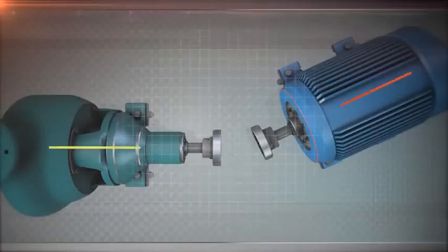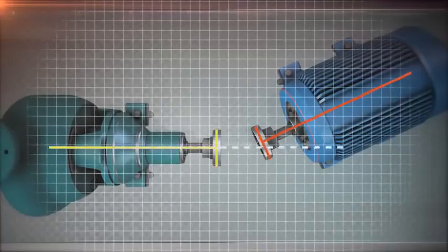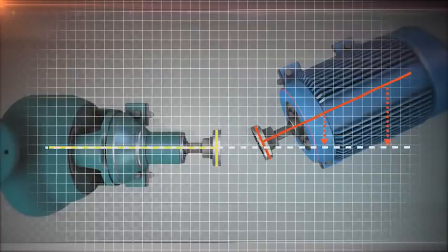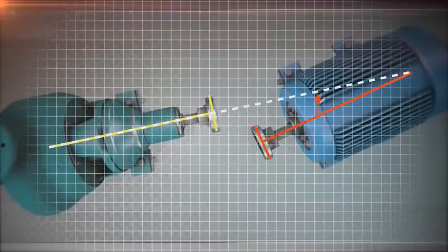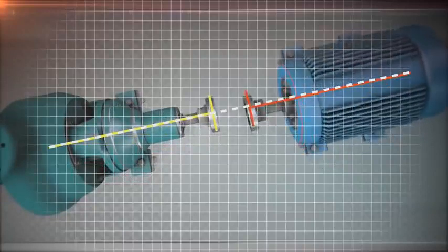or make an optimal move, which is usually the best option because it saves time and does not require working on the structural components of the machine or its base. An optimal move means making a small adjustment on the stationary machine to eliminate the need for the impossible move on the machine that originally became bolt-bound. We simply use the laser alignment system to show us the smallest correction.